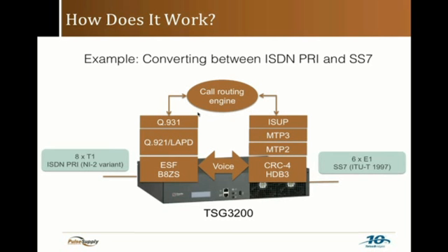Now, if we look on the right-hand side, if you recall, the requirement is to interconnect using E1 interfaces. So here also we have a physical layer which is different from the T1 interface. Typically for E1 links, we're using HDB3 line coding, and the framing can use CRC4 or no CRC. Here I'm just illustrating the use of CRC4, which allows for a cyclic redundancy check on the E1 frames that are transported. Now the network on the right-hand side uses SS7 signaling.